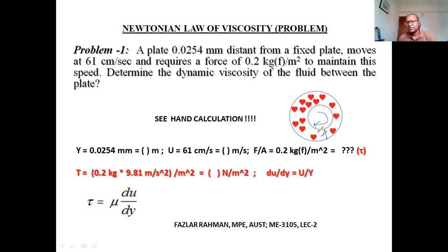So here is also an application: what type of fluid you need to rotate this shaft with a certain velocity. For example, you are working in a manufacturing company, they make the journal bearing. This type of bearing is called journal bearing. So you need to figure out what happens if you use too dense a fluid, then you need higher torque to rotate this shaft.